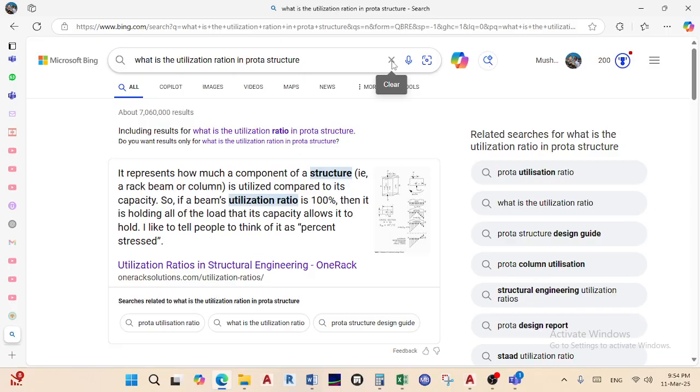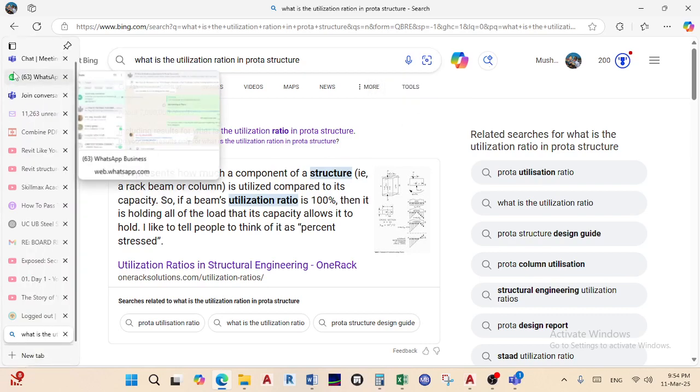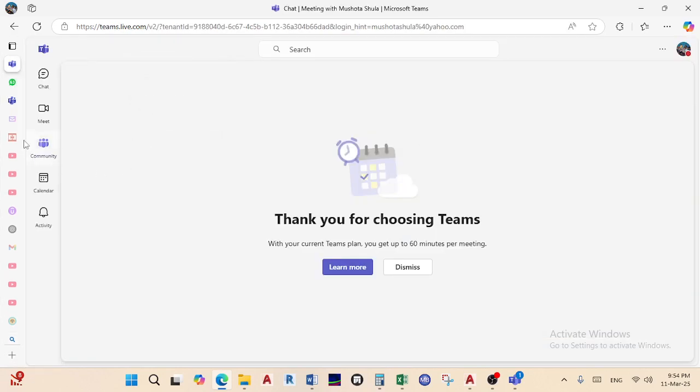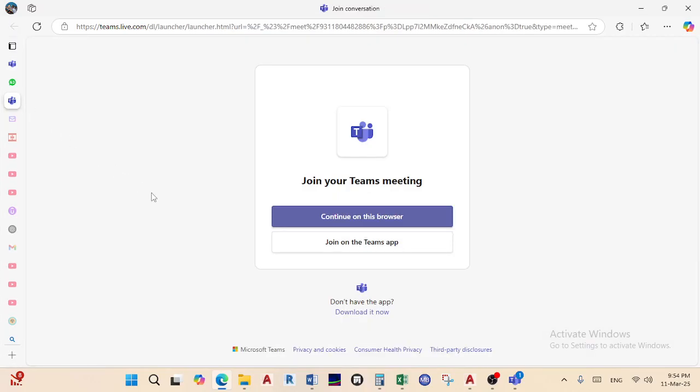Otherwise, if what is required is greater than what is provided, then you have a factor that is more than 1. And in that case, what you mean is that you require more reinforcement, but you provided less. So the reason why it has to be less than 1 is because you need to provide more reinforcement than is required.